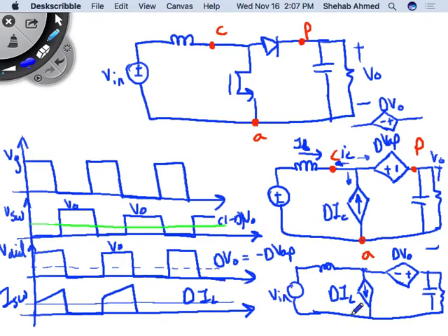At steady state, what does the inductor look like? Short circuit, right? Steady state, inductor is short circuit. Let's go back one step. You can go back and find the transfer function, correct? You will do that for a bonus. This transfer function is not just steady state, it's steady state and dynamic response. The transfer function gives you the time domain response of the circuit. But if I want a steady state solution, it should bring us back to what we derived initially.